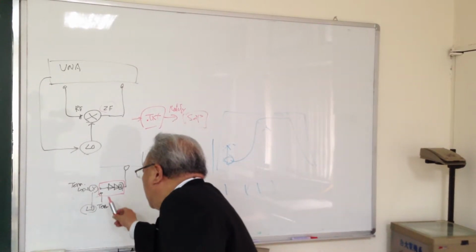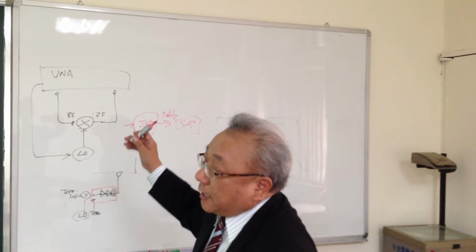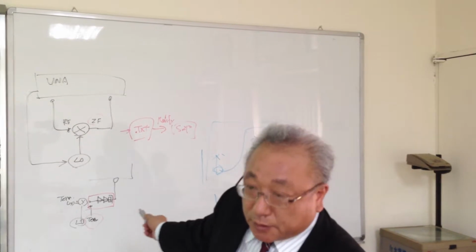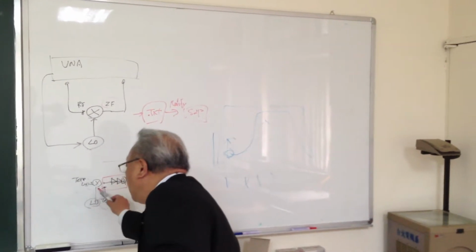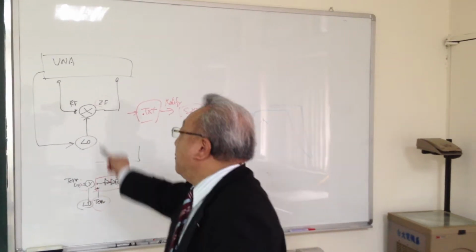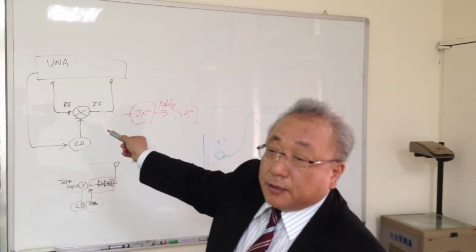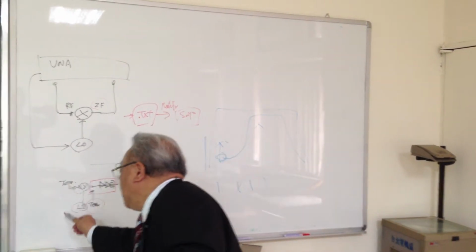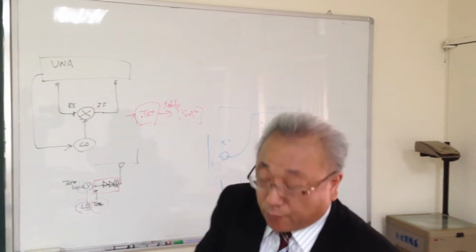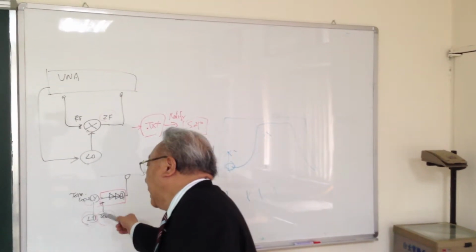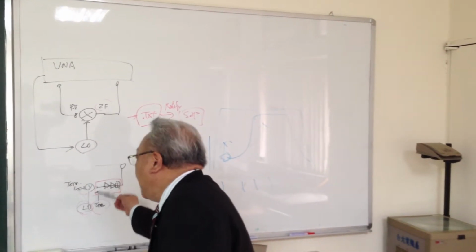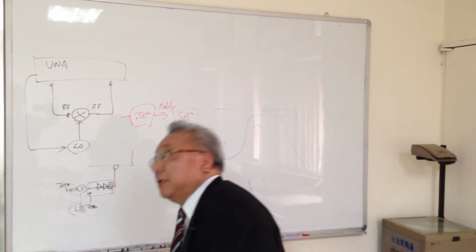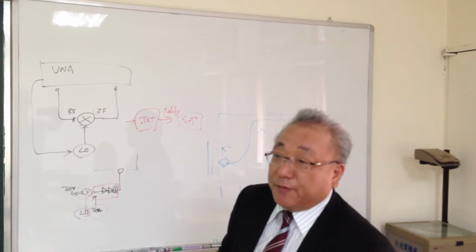To calibrate the receiver, you calibrate the receiver noise, then put in a DUT, and terminate the input. Input meaning the RF port. Then you can measure the noise figure. And at that time, you have to input the LO signal to keep the operation condition of the mixer. That is the current mixer noise figure measurement process.